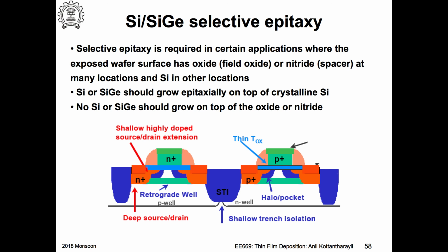So what is the difference between monocrystalline and polycrystalline silicon? Correct, there are grains, a lot of defects. Will that help? The etch rate will be different. If you have monocrystalline and polycrystalline, the etch rates will be different.